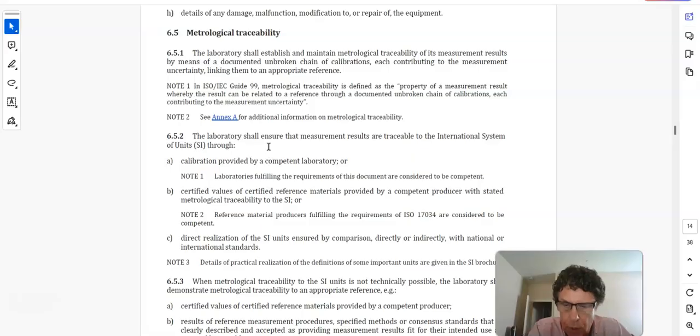Everything was good on 5/1/2024, and on 6/1/2024, it wasn't good and it was out. Your 1 gram didn't weigh 1 gram in accordance with the uncertainty of measurement. So you call a calibration company to come out and fix your balance. But now you have a month's worth of data that's in question. So how often should you check the reference weights of your balance?